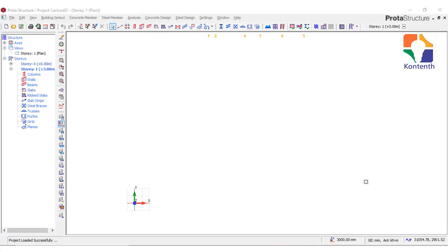Now, before I go into modeling and doing my structural analysis and design, I always like to do my design settings, which is what I would encourage you to do. Do your design settings before you even start modeling. This will save you from a lot of things, and it would save you from different errors. You wouldn't want to imagine a case where you already finished modeling and you just rush to designing analysis without your proper design settings. So now there are design settings we would go over now, which are the slab design settings, beam design settings, column design settings, foundation design settings.